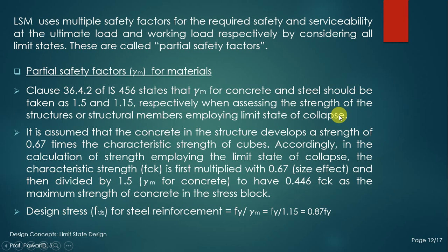So when you use materials like concrete and steel in the limit state method, the partial safety factor for concrete is 1.5, and for steel it is 1.15.